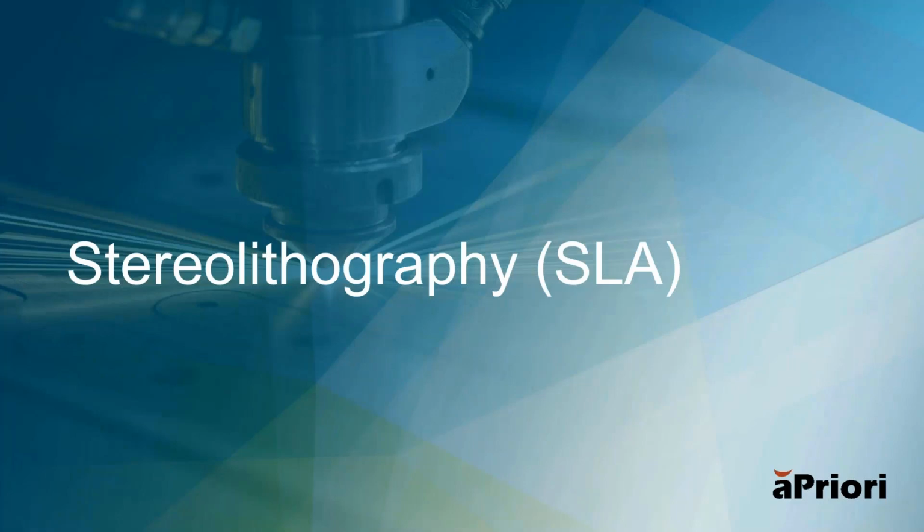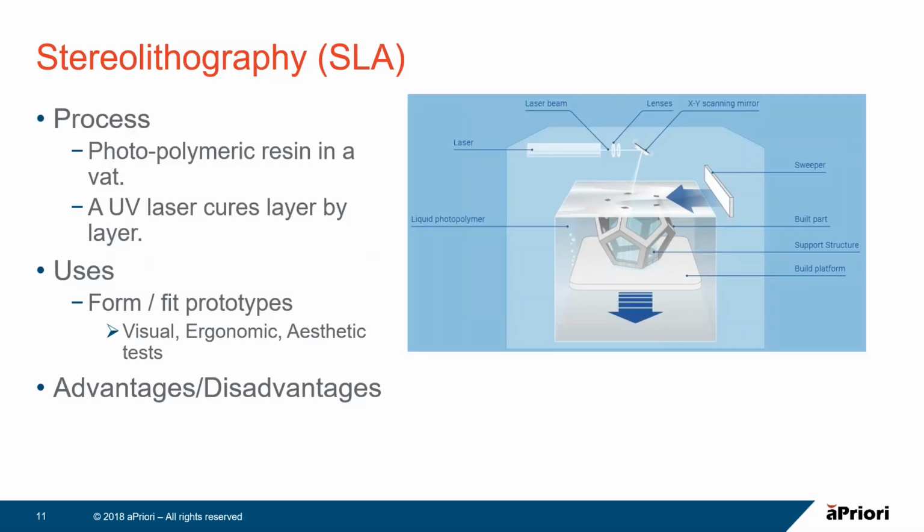The next process is stereolithography, or SLA. And this time, again, we're using a photopolymeric material. Only this time it's not being deposited from a printhead. It exists in a vat, and a UV laser cures it on a layer-by-layer basis.